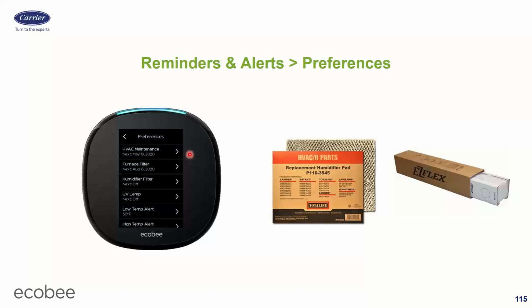Now, with that being said, if the consumer is on a maintenance contract with your dealership, do not put any timer in here, because you don't want the customer to get a reminder from the thermostat when, say, May 19th comes along. I want the customer to get scheduled with me, the dealer, for my maintenance when I pick.